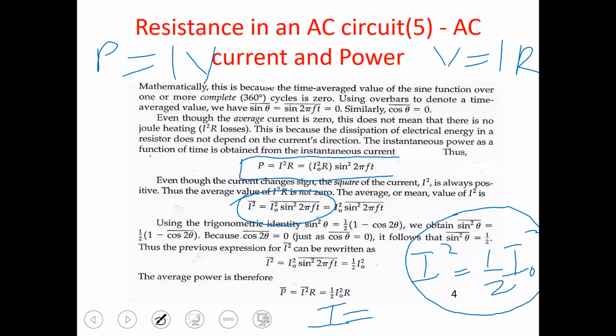And it will not just be the square root of both sides, it will be I RMS. Root mean square. You square it, you average it, and you root it. Then that is what has been done. So if you read through this place, you will see that some averaging has been done, and in the long run, what we have here is I naught divided by root 2.